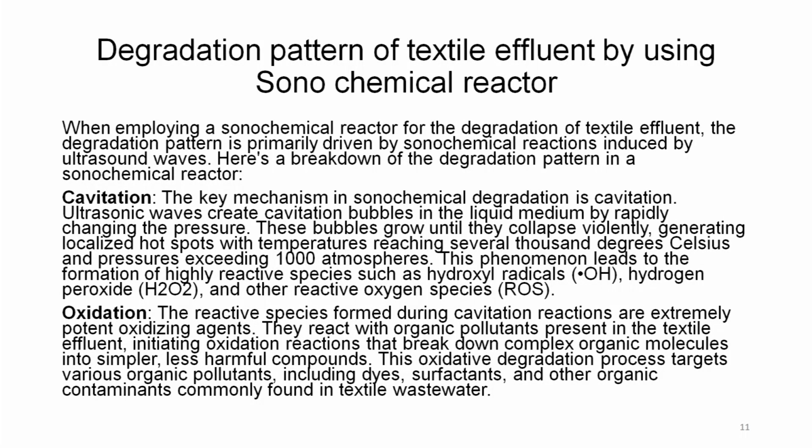When employing a sonochemical reactor for the degradation of textile effluent, the degradation pattern is primarily driven by sonochemical reactions induced by ultrasound waves. Here is a breakdown of the degradation pattern in a sonochemical reactor. Cavitation. The key mechanism in sonochemical degradation is cavitation. Ultrasound waves create cavitation bubbles in the liquid medium by rapidly changing the pressure.